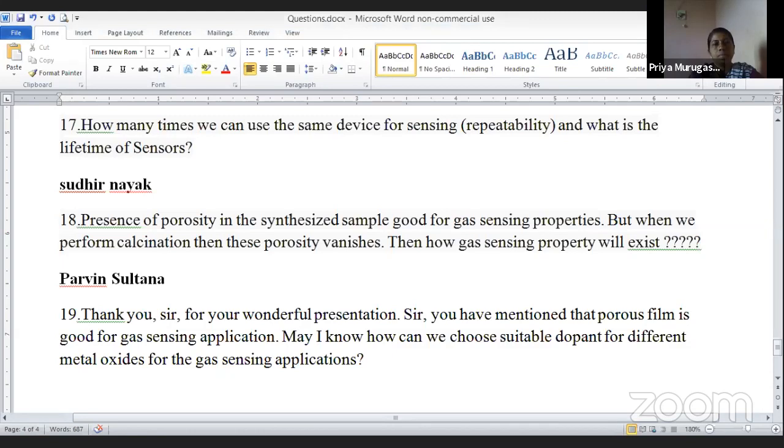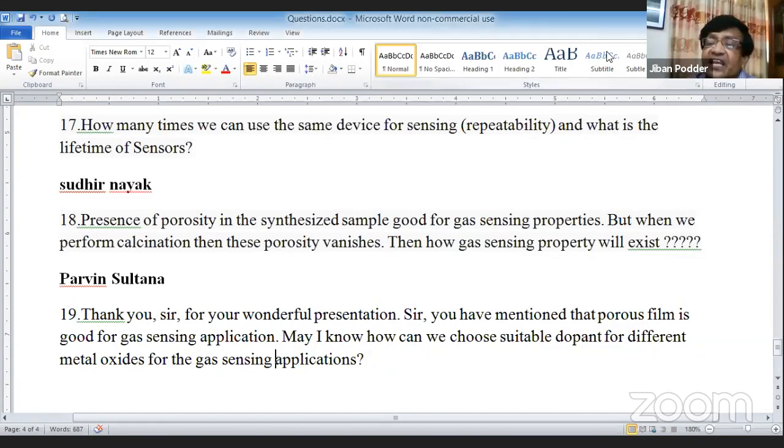If we want that, then we go for calcination. Ultimately by calcination we are removing all the unwanted impurities from the prime matrix and complex material, so for that purpose we cannot produce the porous structures. For porous structures we always need thermal reactions, and then only can we produce nanostructures with porous structures. That is suitable for gas sensing purposes.